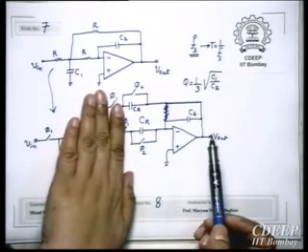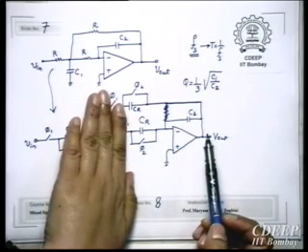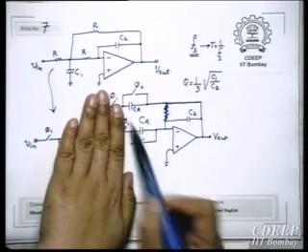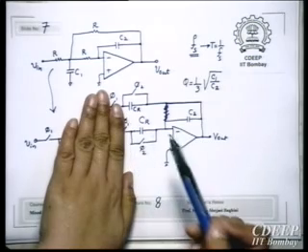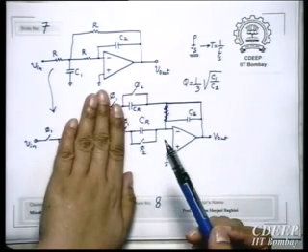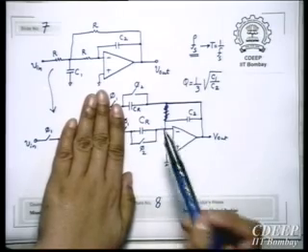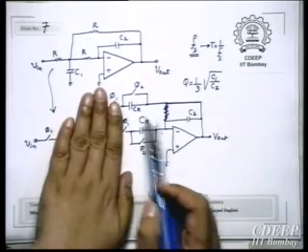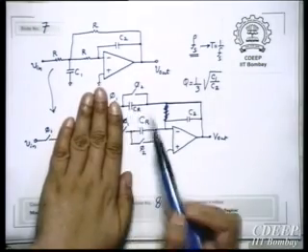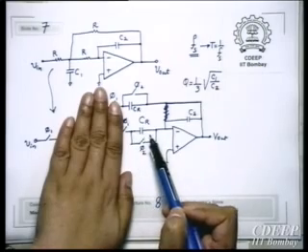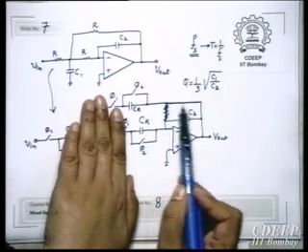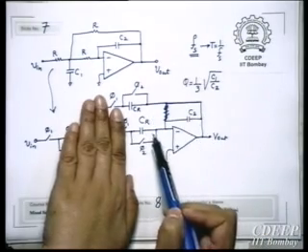Now look at this situation in phase phi 2. You have these 2 nodes connected. Therefore, it is likely to have some charge sharing. The reason is because when these 2 are open, you are sure that the entire current will get dissipated here. But when you connect these 2, and this is a path, this charge may come.